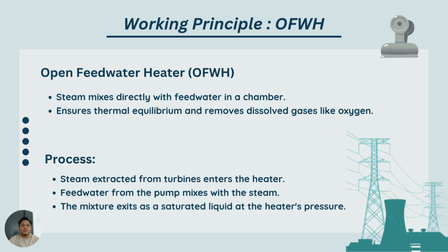So next, here is the working principle for the open feedwater heater. In this type, steam mixes directly with the feedwater in a chamber. This process not only ensures thermal equilibrium but also helps remove dissolved gases like oxygen, which can cause corrosion.